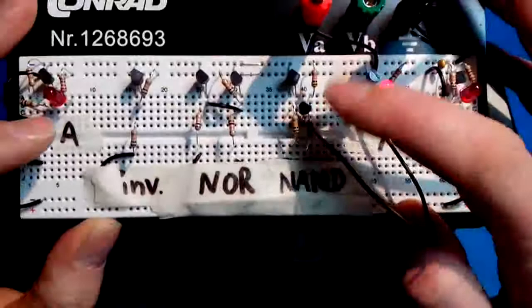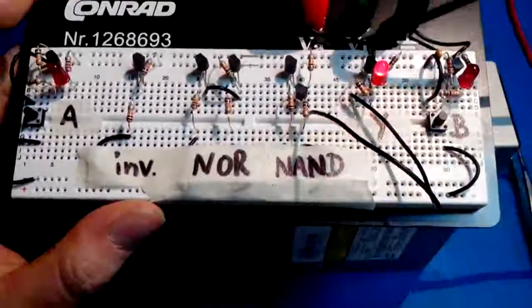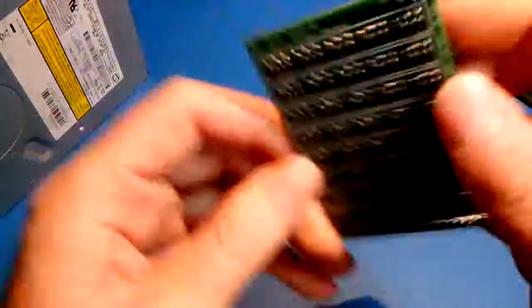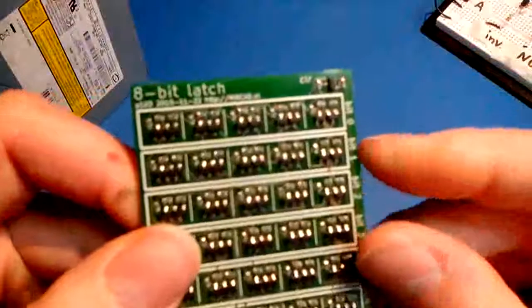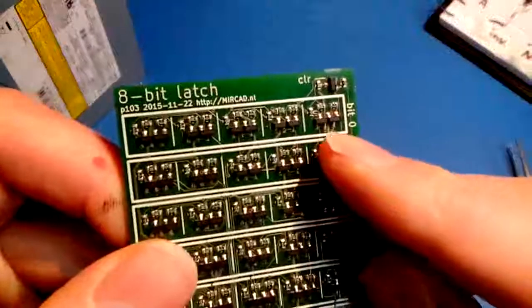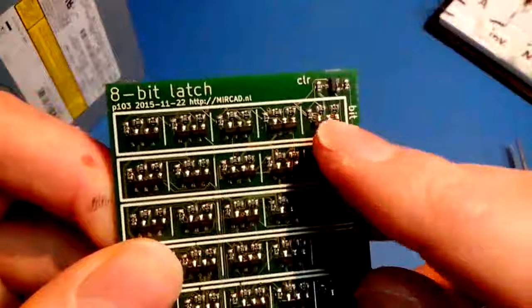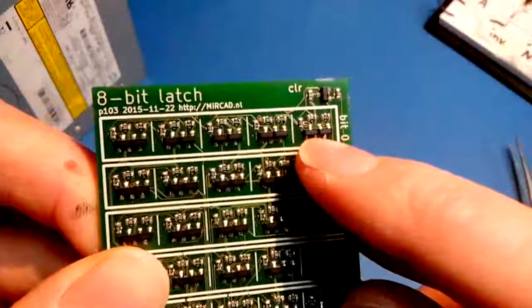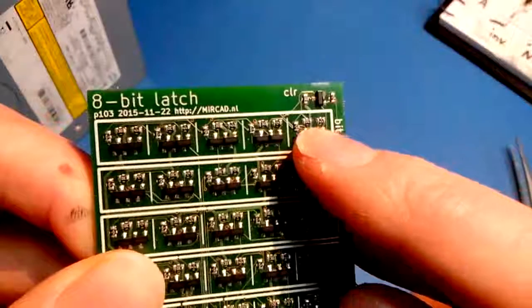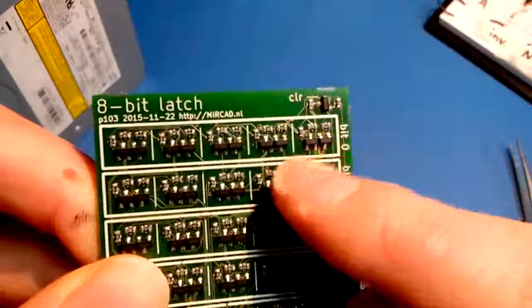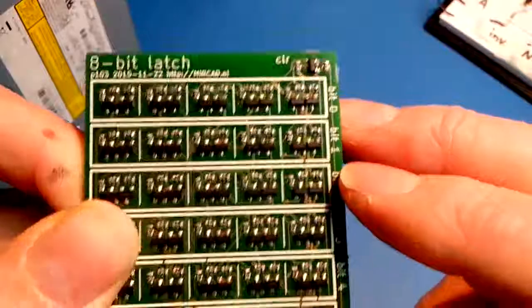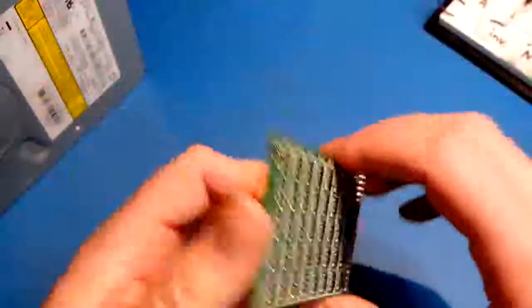So this is very big, but as you can see, 2 transistors, 3 resistors, typical NOR or NAND gate. And if you look at this board, I'm not sure from memory what this is, but in one cell of each row, so in one white cell, you see 2 black things. That's the BC847 transistor, and 3 other things. That's a resistor. So these are NAND gates or NOR gates. I'm not really sure which is which. So that's how it works basically.